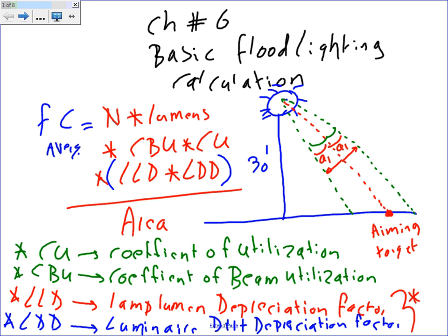So, to summarize, you have a floodlight. The only thing I want you to know about it is that you mount your floodlight usually high, instead of 10 foot, usually 30 foot or higher. It's shooting light, and you can direct the light based on this line here. That's the aiming. And then the angle above or below this aiming line can get you more or less lumens.